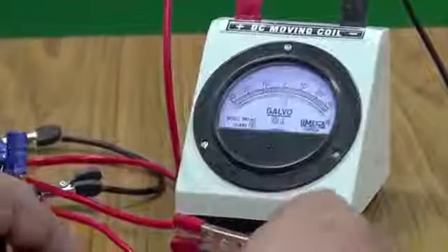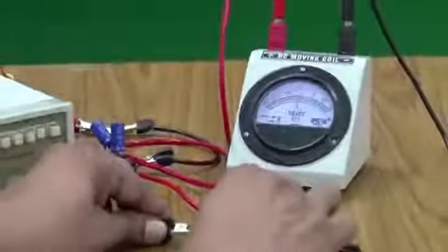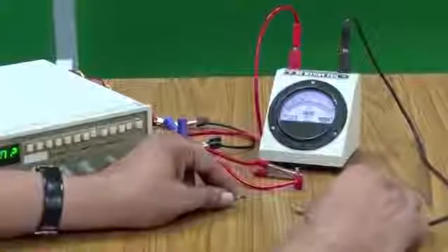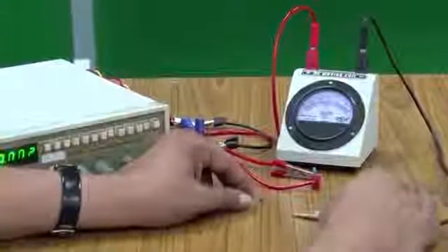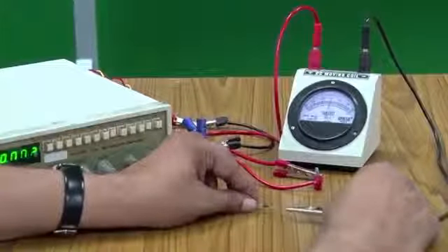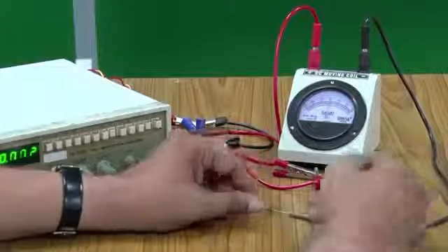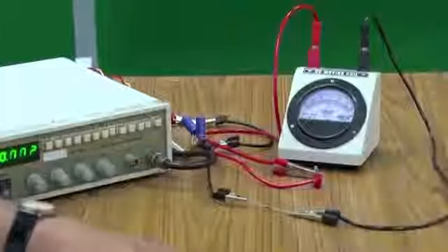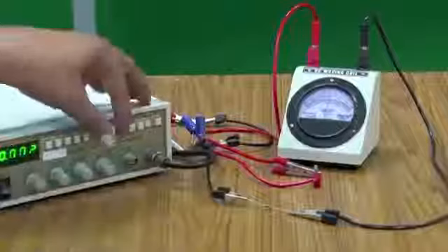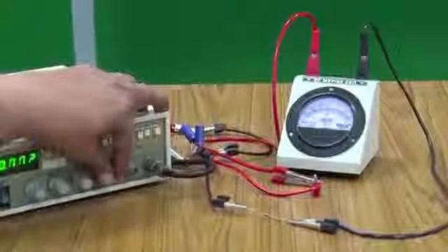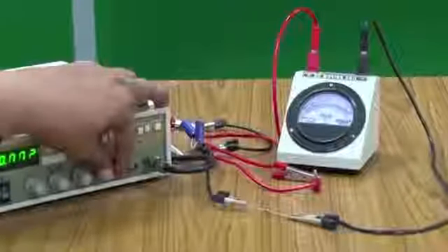So, that shows that this assumption that we had taken, that just forward bias and you have large current, is not true. You have to supply some initial voltage, after which that IV characteristic, the exponential part, starts, only then it works. So, let me increase this voltage and you can see that yes, now it has started going.